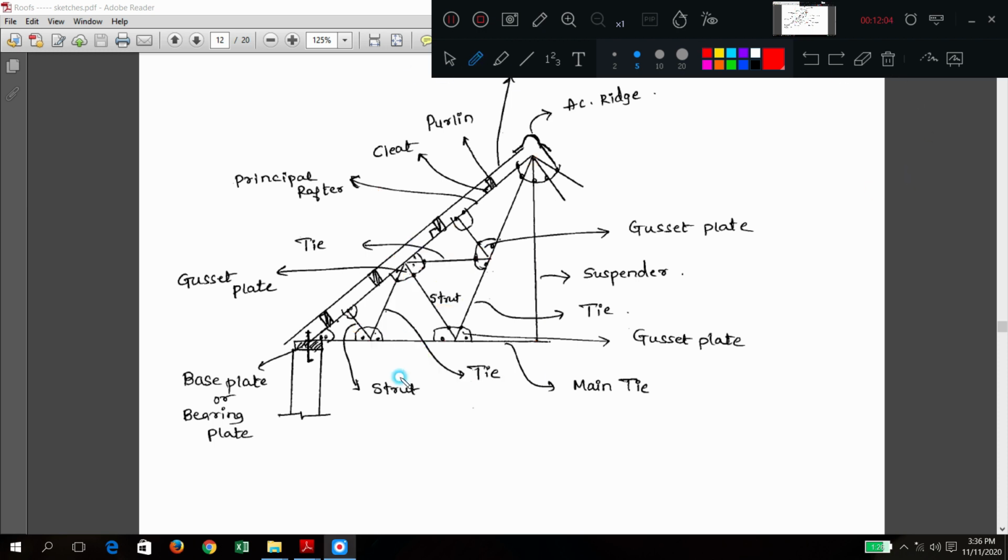Now here are very important terms. All the connections, try to remember, are joined using gusset plate connection. Very important. Wherever joints or connections are there, these are connected by gusset plate, with nut and bolt arrangement. Here also one big gusset plate is there. So there is nut bolt, rivet connection, everything is there. Simple, no? In the wooden truss you had the three-way heel strap connection.